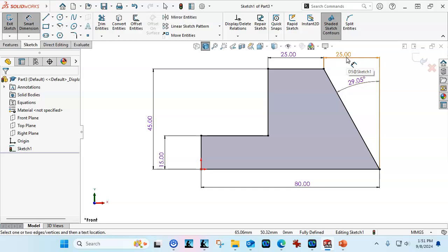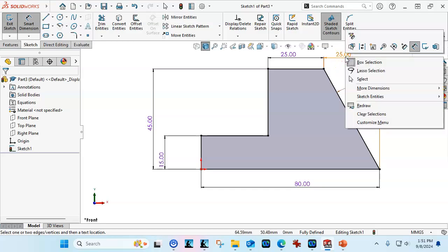Now, manufacturing this part, we know that if we take it over in the assembly and the 25 millimeters is the critical dimension, then we need to stay with the 25. But for setting this up for manufacturing, 29.05 somehow isn't as easy as grabbing an angle block and setting it up and being pretty close to machining that geometry. All right, so we need to analyze this in the assembly.